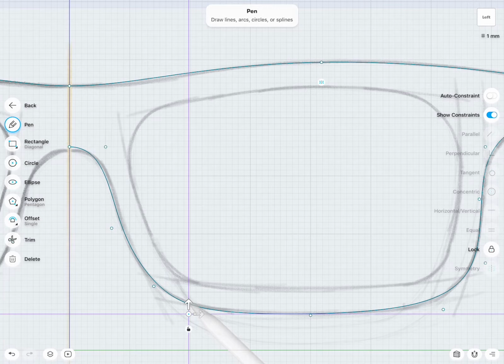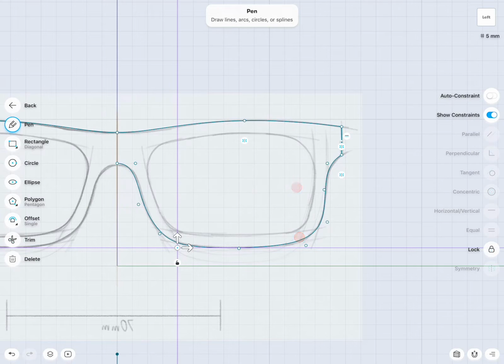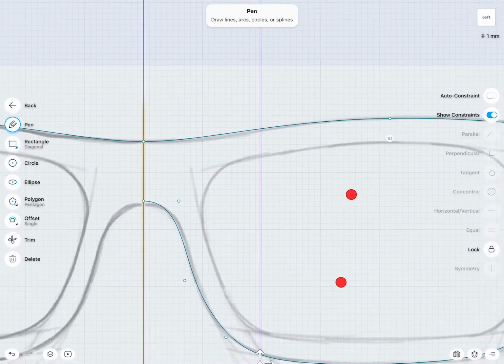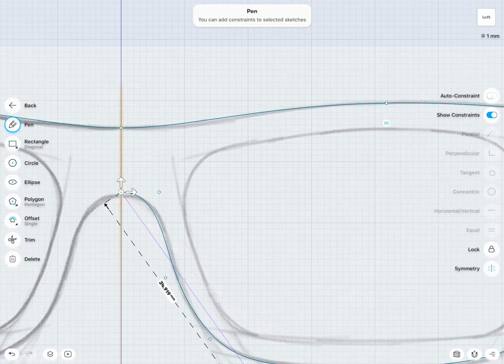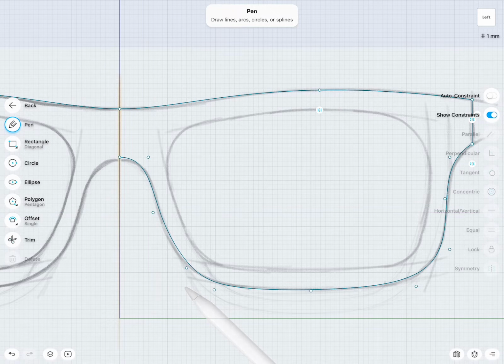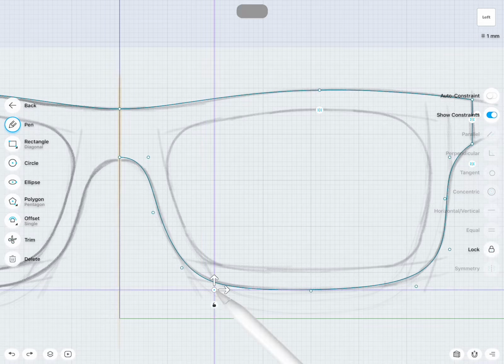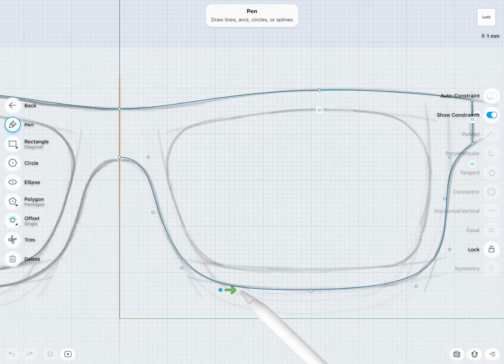And you saw on the first curve I created, I only needed 5 points and I had exactly what I want. And here for the lower part, I need more points, but then I get actually also what I need. Maybe we can move this up a little bit to there and there. Very good. In regards to corner points, you see the more I bring points together, by the way, the more I'm tightening actually a corner too. So it's another cool creative element of the CV, the control point curve.